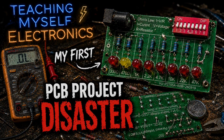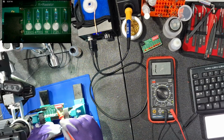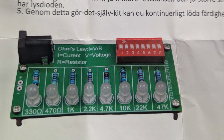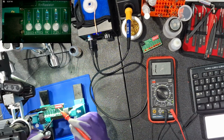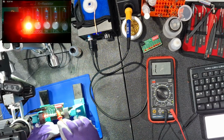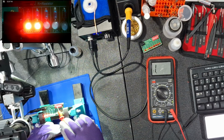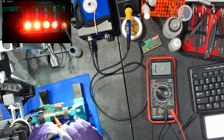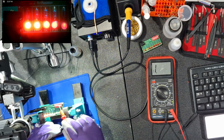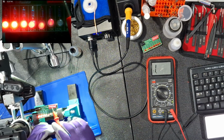In the last video I did, my first PCB disaster, I put together this PCB project that I bought, and it's a very good demonstration to show you exactly how resistors work by using LEDs, different value resistors, and a dip switch. So I'm just going to start off by turning on some of these LEDs by using the dip switch. And you notice LED 1, 2, 3, 4, 5. You notice 1 is very bright, 2 is bright, 3 is bright but not as bright as 1 and 2. 4 is bright, and down the line it's just getting dimmer.